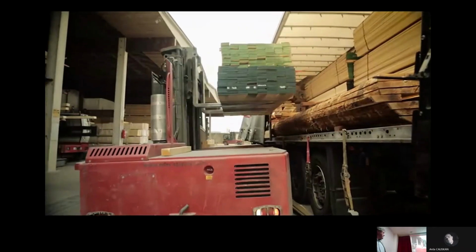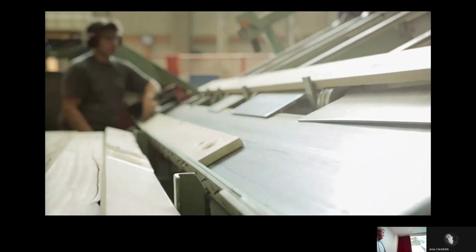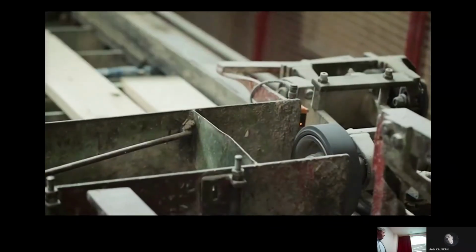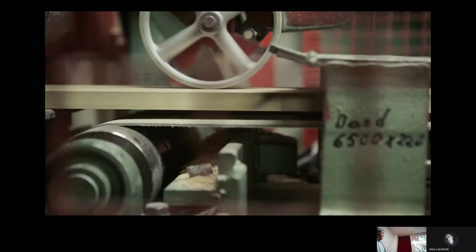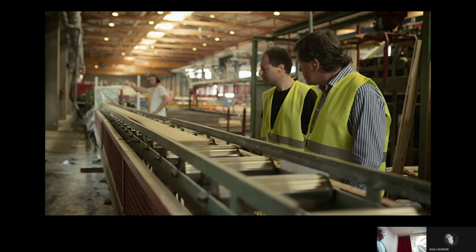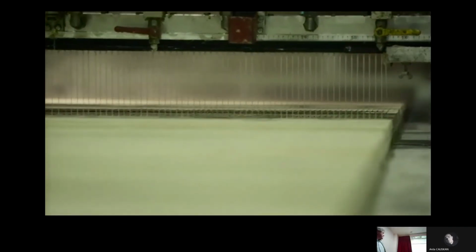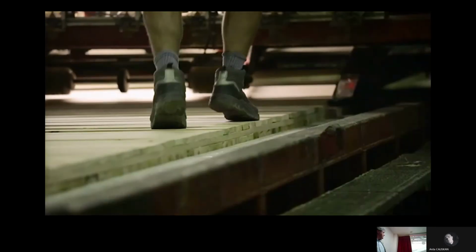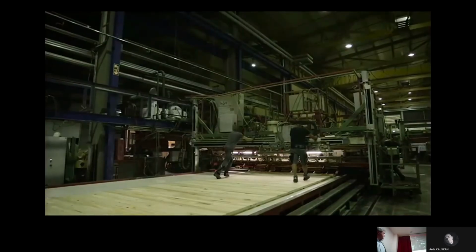We are Tim and Timber, and we are based in Bavaria, the southern part of Germany. At the moment, we are manufacturing the CLT panels. The first step in producing CLT is to have endless boards, which are cut in the lengths we need. The method we use to produce an endless board is called finger jointing. After the finger jointing, the boards are glued crosswise. Most of my project will produce panels in dimension of 40 meters in the length and 4.4 meters in the width. So it helps our expert wide and extra long.